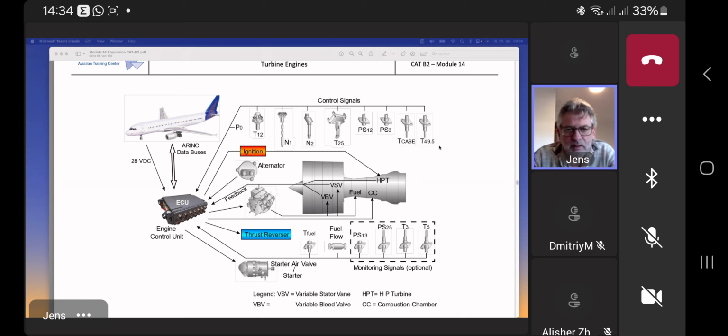If the compressor, for example, does not reach the requested compression ratio, the engine will react by enhancing the fuel flow to enhance the RPM, so the compression ratio is reached. That gives you an indication for the performance.